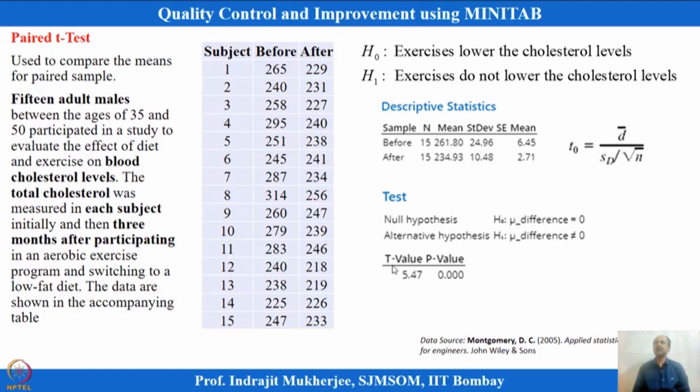Like in manufacturing, we will find that I have hardness testing machines of different types with different tips. So, when I use different tips, whether readings are different or not, to confirm that we also do paired t test, because the sample remains the same. So, on the same sample I am using two methods. I want to compare which method is giving me a higher reading or whether they give the same readings, or the same hardness. So, for that also this type of analysis is required. So, this is all about paired t test.